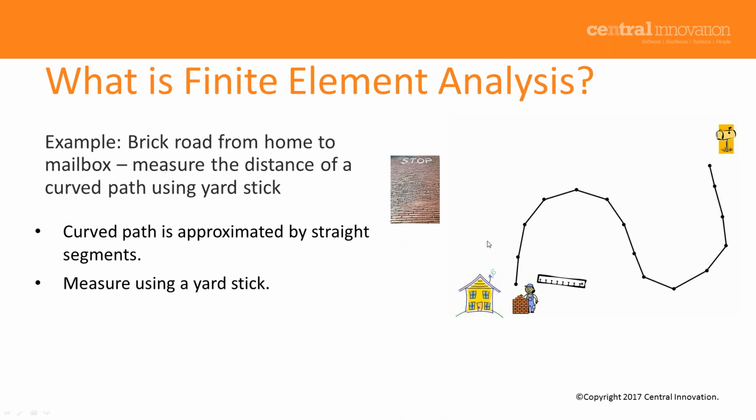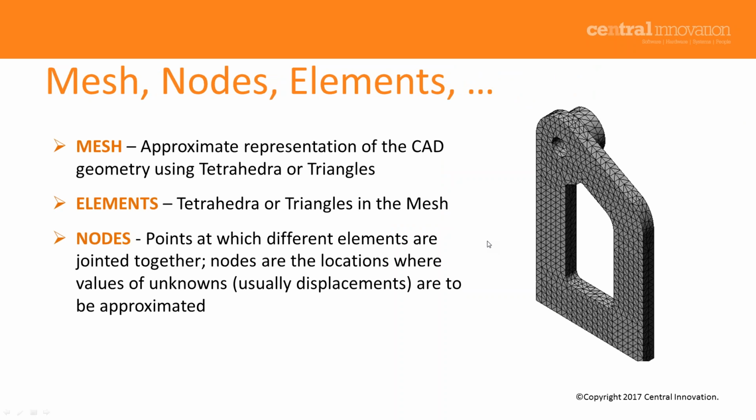using. We have the same concept when we're doing simulation or doing FEA analysis. You have a CAD geometry and you need to represent it as an FEA model or finite element model using your, let's say, measuring stick, which is called elements. Elements are basically tetrahedra or triangles sitting in your model, and a network of them, which is called mesh, is simply going to represent it. Therefore, a smaller triangle size, when it's going over the curves, can estimate it better.